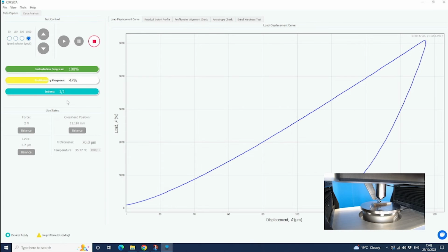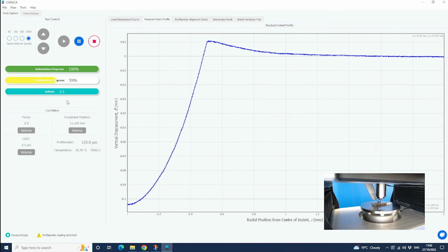And again, at the end, we'll see that test diagnostics box, where if we have a problem, we would have a yellow warning. The final thing, that X and Y scan, is there to detect anisotropy. With in-plane anisotropy, you lose the radial symmetry. So in scanning in two directions, we hope to pick up that they are, in fact, two different profiles. This will give us some information about the degree of anisotropy, the direction of anisotropy, i.e. which direction is harder and softer. We're in the process of developing tools to extract direction-dependent material properties.